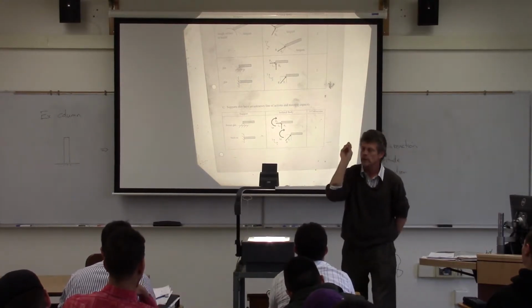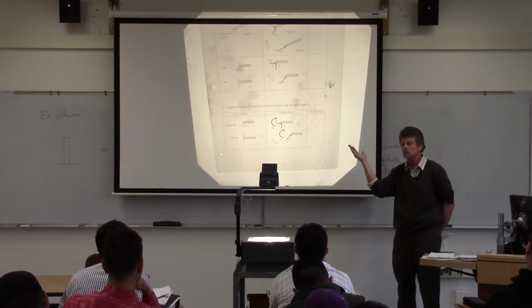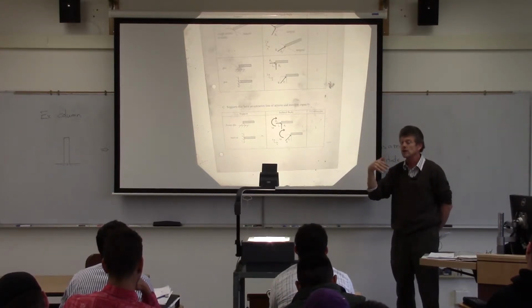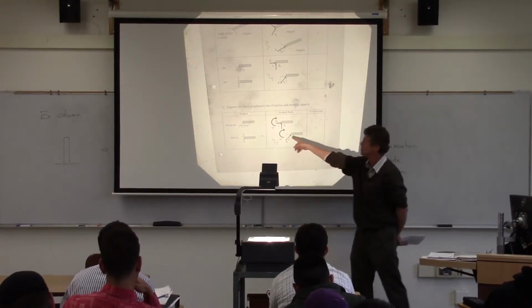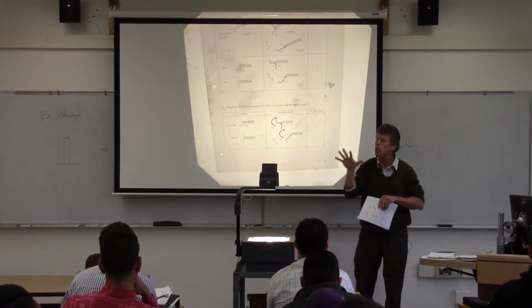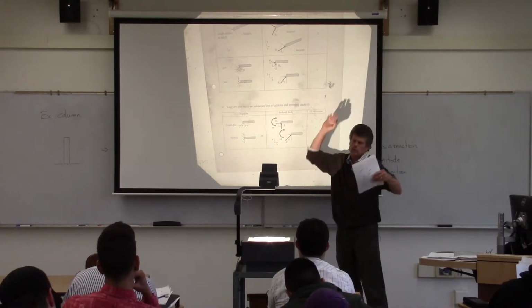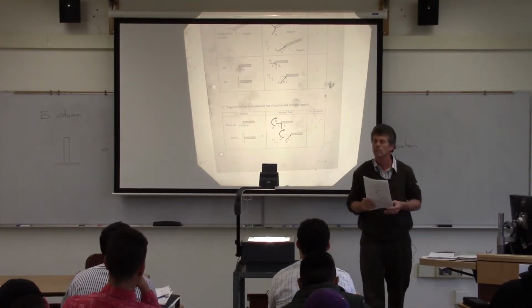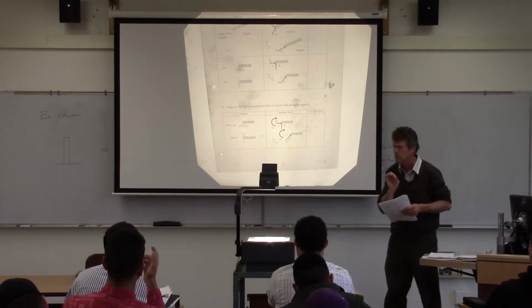And the nice thing about that is, remember we talked about that when we were doing particle equilibrium. I can choose the wrong direction, and the sign will correct me. And we're going to have that same situation here. If I choose the wrong direction for that moment, and I put them in the equilibrium equations properly, if it comes out minus, then it says, oh, I just chose the wrong direction. The moment should be restricting motion. It's restricting rotation.